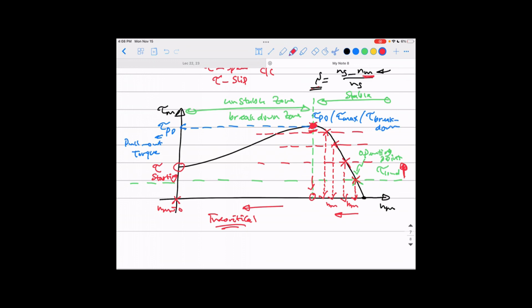This is the lowest speed you can hit, because that is the maximum torque you can develop. More than that, you go into the unstable region, and that means the machine is breaking down. We don't need this, and we do not let the machine go there.